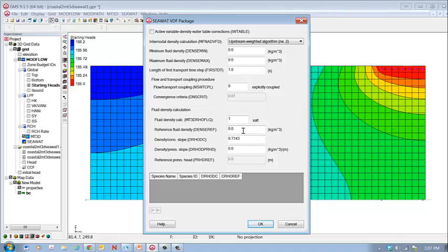Okay, so what you need to do here is use a reference fluid density of 1000. That is the density of the water when the concentration of salt is 0. And the density factor term F on the slide is this term here. And there's the value. So that's the default value. We'll go with that. So that's what we need to do for this slide.